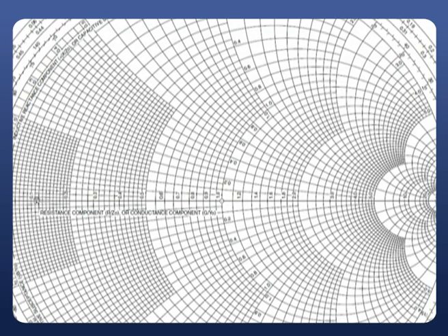Here clearly all these circles are resistance circles, and the values of those resistance circles are printed on the horizontal line. Now if you observe, this is the extreme right point to the observer. This extreme right point is meant for the r equals infinity circle. R equals infinity circle means a circle with zero radius. Zero radius is completely a point. So where I am showing is said to be the r equals infinity circle, right?